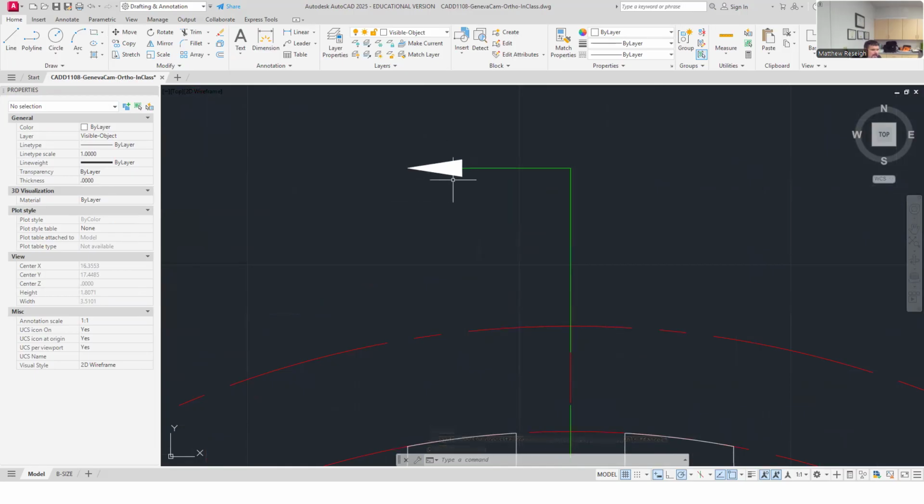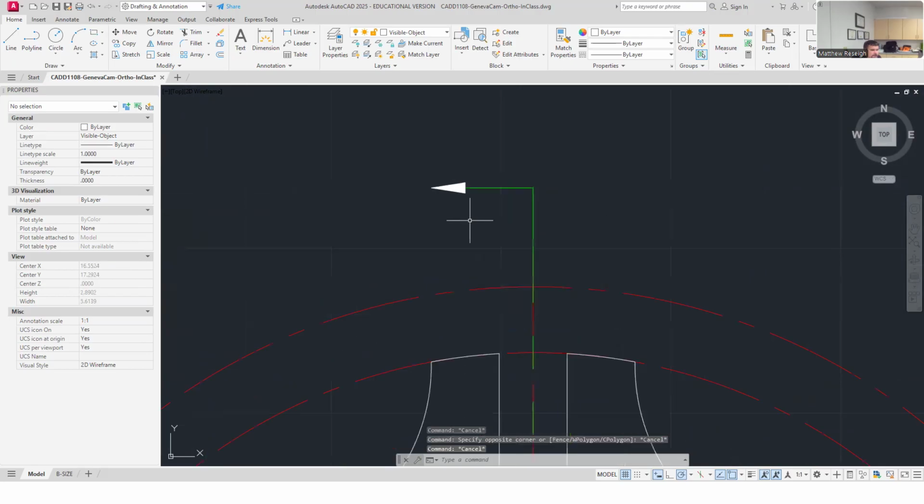These were polylines that we created these arrows with, and I'm going to jump into that and just address what I told you. If you create them in here, I use my polyline and I made my width 0.08 because that's double the width of a normal arrow. This thing needs to be a double size arrow. So I used a polyline and I set the width at 0.08, and that was the starting width, and then the ending width was 0, and then it wants to know how long it is.